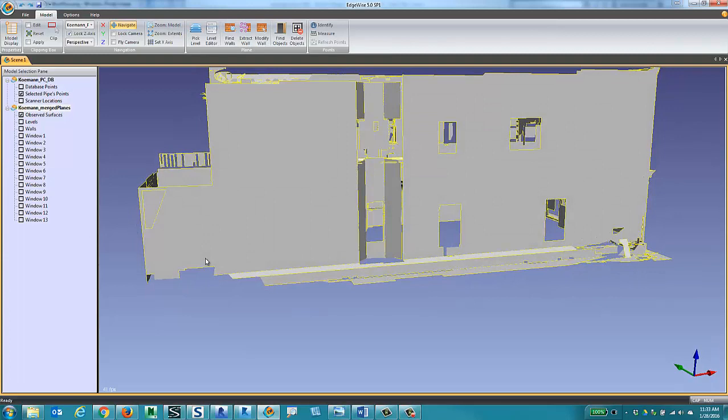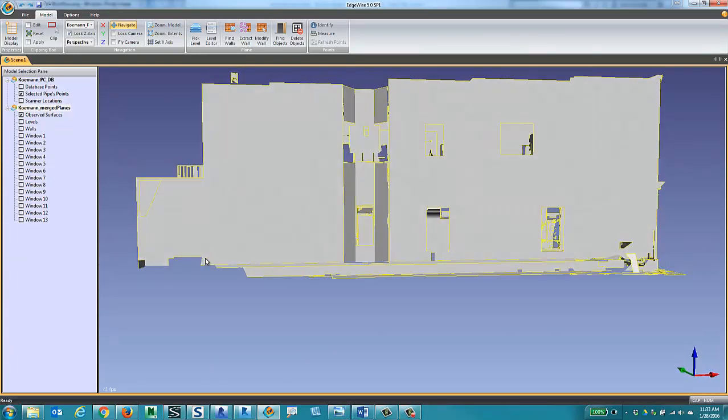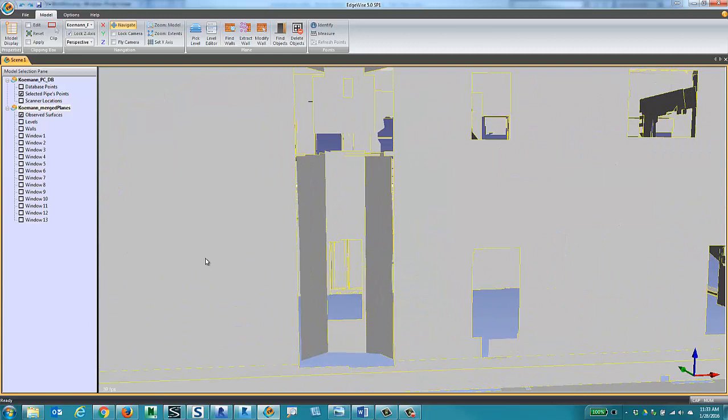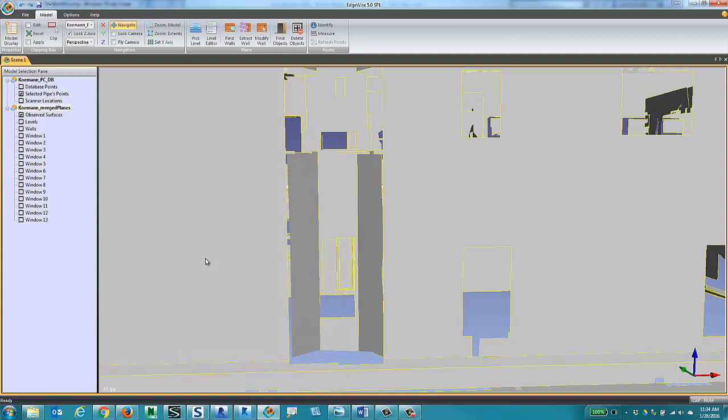Okay, so just looking at the window situation here, this tool works well if you have standalone windows, but acts more as a placeholder for those windows. So the nice thing about this is that it'll come in the location of the opening that it's determined in Revit, and we'll create a Revit window. You would probably do some tweaking to that window, which we'll talk about through Cubit and Pointsense in a little bit here.